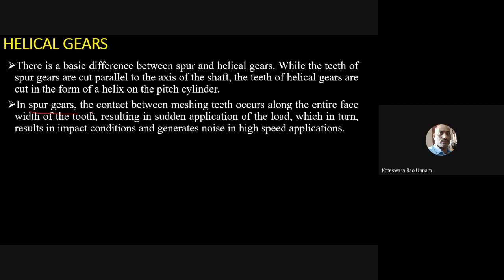In the case of spur gears, the contact between meshing teeth occurs along the entire face width of the tooth, resulting in sudden application of the load, which in turn results in impact conditions and generates noise in high-speed applications. Because your teeth are cut straight, parallel to the axis, whenever one tooth on the pinion comes in contact with the tooth on the gear, the contact is sudden, and it comes in contact along the entire face width of the tooth. So this will result in impact kind of loads and also generate a lot of noise.